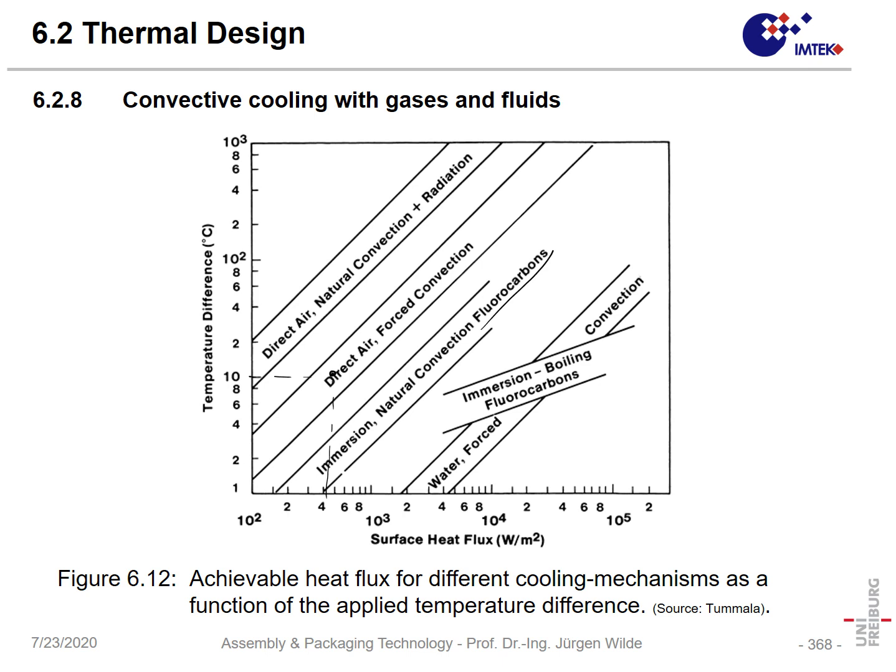So again, it's a linear behavior, and it's even better than the forced air convection, because that natural convection of the fluorocarbon has a higher specific heat capacitance per volume or per kilogram of that material. Then we take forced water.